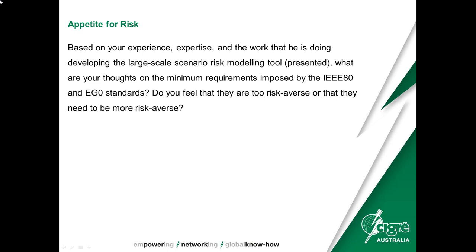He determined from the data that he studied that there were two current sensitivities, one of them that represented more or less the whole of the population, which he referred to as the 50 kg criteria, and one that represented more or less the workforce, which was referred to as the 70 kg criteria. Even those facts, how Dalziel did it and what came out, aren't well understood.